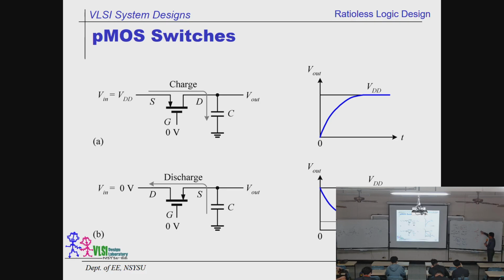Okay, we use the P device on the top to pass 1 because 1 stands for the VDD, and this is our load capacitance that's over there. And we're going to use an N device to pass 0. That means to discharge it. So we are going to have our first design, a very famous and also the most fundamental design in digital. It is called an inverter.